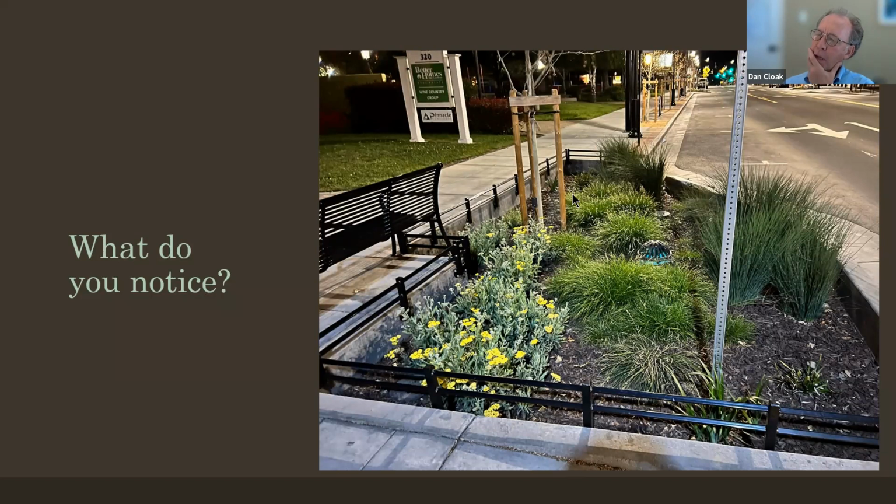The issue here is that this needs to be flat. The elevation of it is determined that you want it to be 6 inches below the inlet, which is obviously here where the runoff comes down into it. So there's your point. Everything needs to be that elevation. But as you move up toward the sidewalk side, that means that you end up with significant reveal here. And they've done that by either a high curb or a low wall.